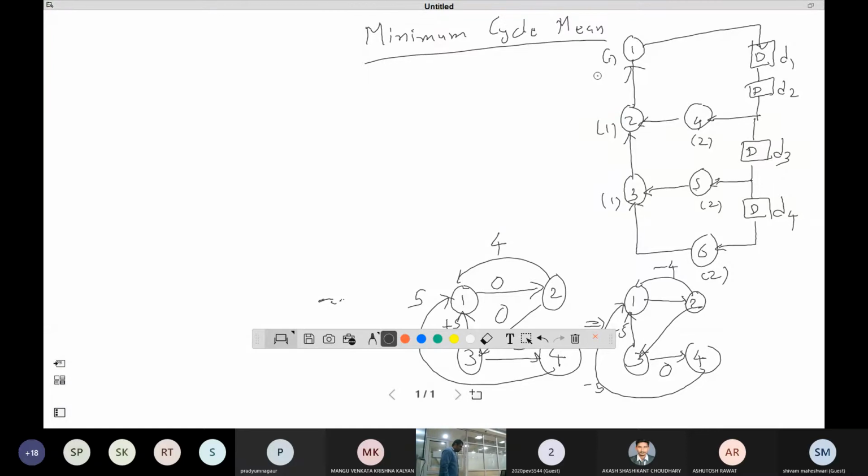So, yesterday we have just seen two methods of the iteration bound, where we can find the iteration bound through loop bound as well as through the LPM method, longest path matrix. I believe that you have tried out that example where you created all four matrices, and then from that matrix the diagonal element that you need to take care of, along with which matrix you are talking about, you need to divide with that value. Okay, and whatever the maximum value is there, you need to consider as your iteration bound.